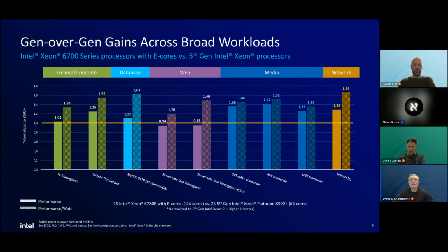This is a performance comparison, and the baseline in this slide is the previous gen, 5th generation of Intel Xeon processors, top bin versus top bin of 6th gen E-cores, 144 cores. I'm not talking about 288 cores, it's kind of a special beast. As you can see, performance-wise, it's a moderate speedup between near parity and something like 42%, maybe 1.2x speedup on average.